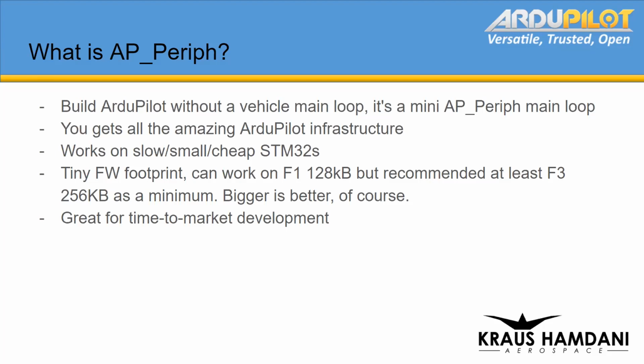Basically, you just build ArduPilot without a vehicle. Normally, if you build ArduPilot, you get all these other things with it, like object avoidance and GPS drivers and IMUs and all these things. But you have a main loop that it runs through to basically check serial ports and all these sort of services it's running. So this is a much more minimalistic version of that, where it has its own main loop. You compile it with AP perf as the target, and it's just its own main loop running just the little small tasks you want.